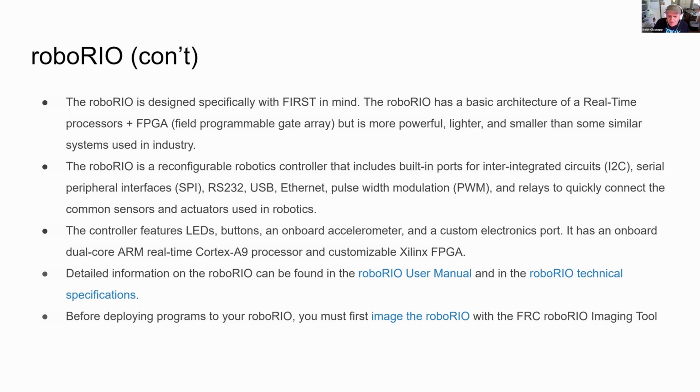We also have something called SPI, Serial Peripheral Interface. Again, we have not used that particular interface, but it's available if we want to. The beauty of I2C is that it's basically a two-wire interface, a clock and a data line, whereas SPI requires clock and data, or in fact two data lines, as well as a control lead. So it's a little bit more complex to get it to work. They also have something called RS-232 that we can use if we want to for things like low-level debugging, but typically we have not used it.